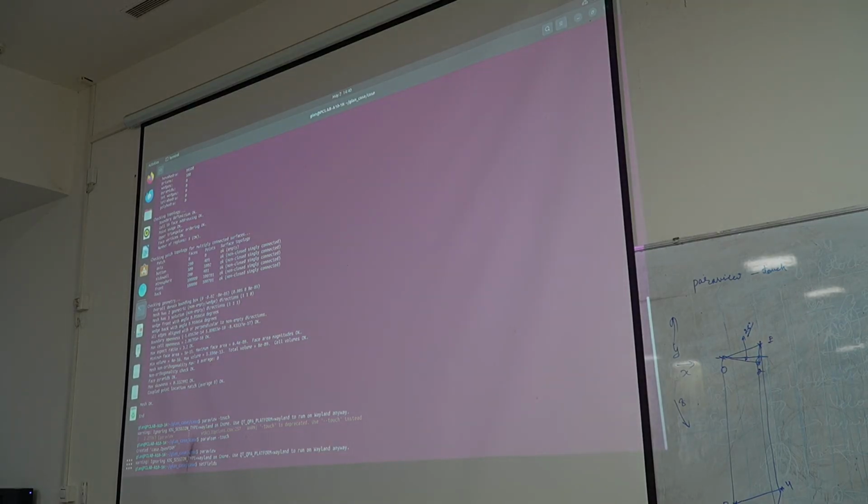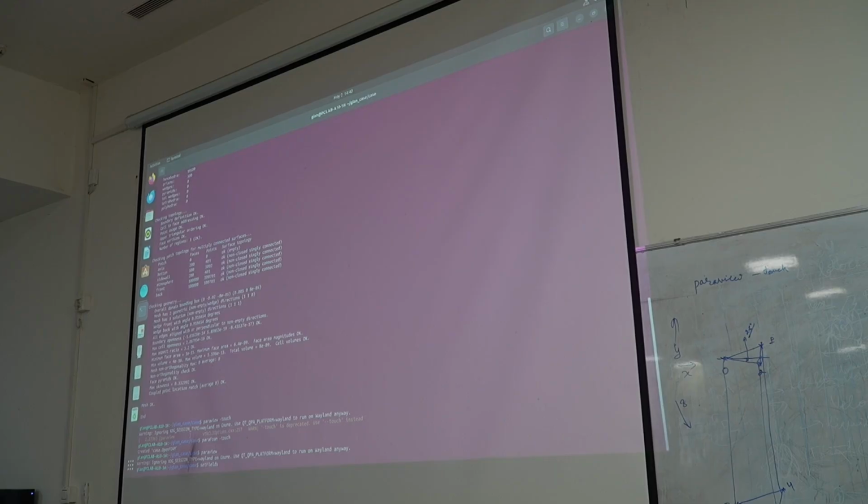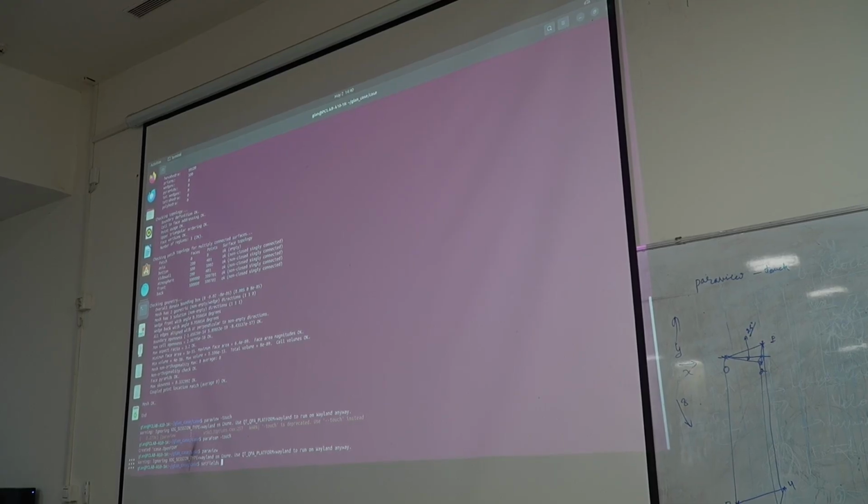Sir, in alpha.org, the internalField uniform 0 means everywhere we have given alpha as 0. That's why later we specified the alpha.water default value as 1. But what if we give 1 here? Then we need not use that default line in setFields. Yes, yes. So we can give 1 here as well.